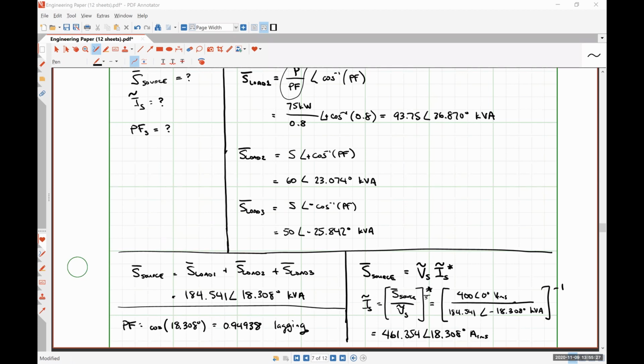For part B, notice that your sinusoids have the same frequency, which means you could convert them both to cosine functions and then add them together, and you would have a single sinusoid of which you could take the effective value rather trivially, just by dividing that magnitude by the square root of 2. For part C, you have two different sinusoids, and they have different frequencies. And so that's going to make things a little bit tougher.